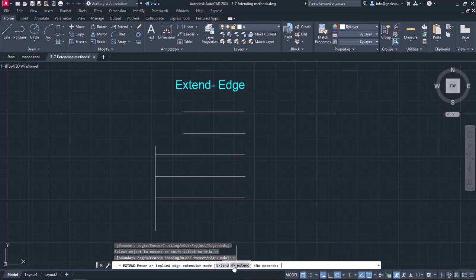In this case, I will select the Edge option and then I will activate the Extend mode. Now I will proceed to extend the lines again. Notice that I can finally extend the lines. When I'm finished, I will deactivate the command. When you finish with the Extend option, it is highly recommended that you activate the command again and return the Edge mode to No Extend. The reason I recommend this is because the Extend mode can create confusion when we extend lines and curves.